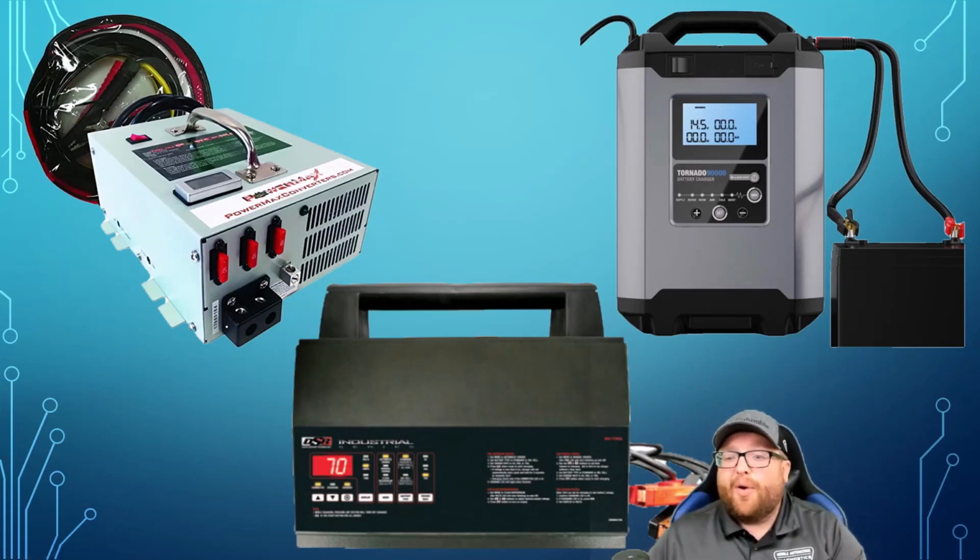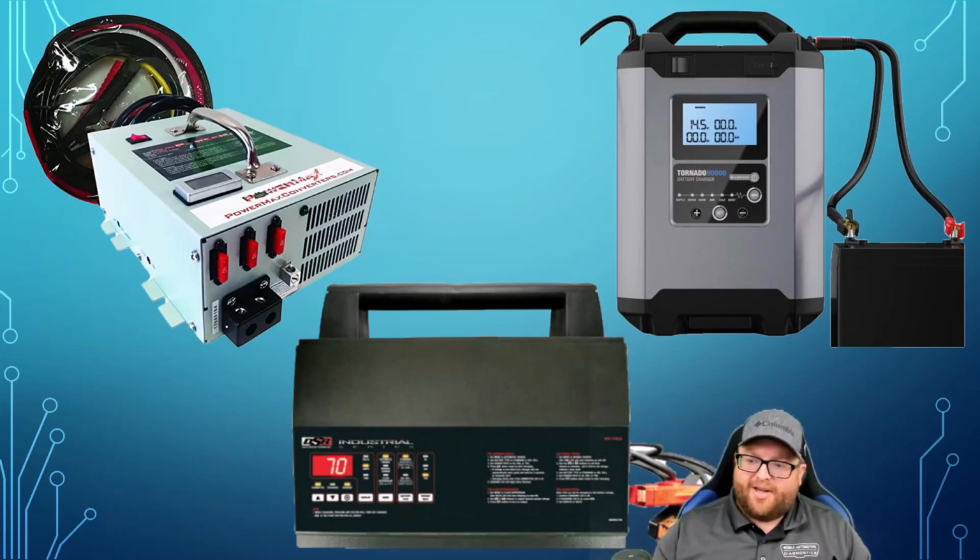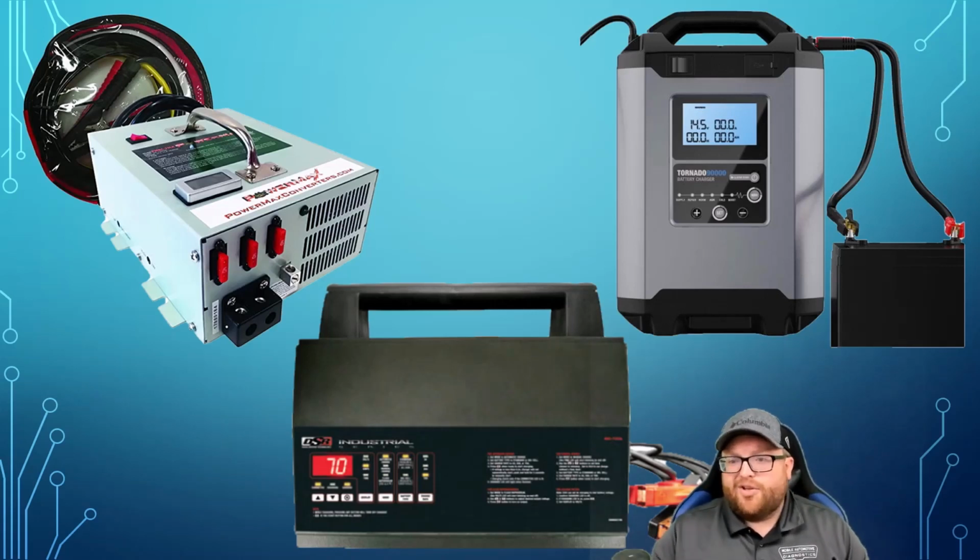So let's say you don't have one of these and all you have is a roll-around battery charger. You can use a set of jumper cables from a vehicle that has a good alternator that we know doesn't have some really bad AC ripple, or some parasitic draw issue or something like that. That could be the alternator. Definitely, if you've got something that's got a good alternator, usually I would use something like a truck that's going to have a big alternator on it. You can use that in a pinch. And a lot of us mobile guys, we actually just use our vehicle. We'll have quick disconnect jumper cables. We'll just use those when we're programming vehicles.